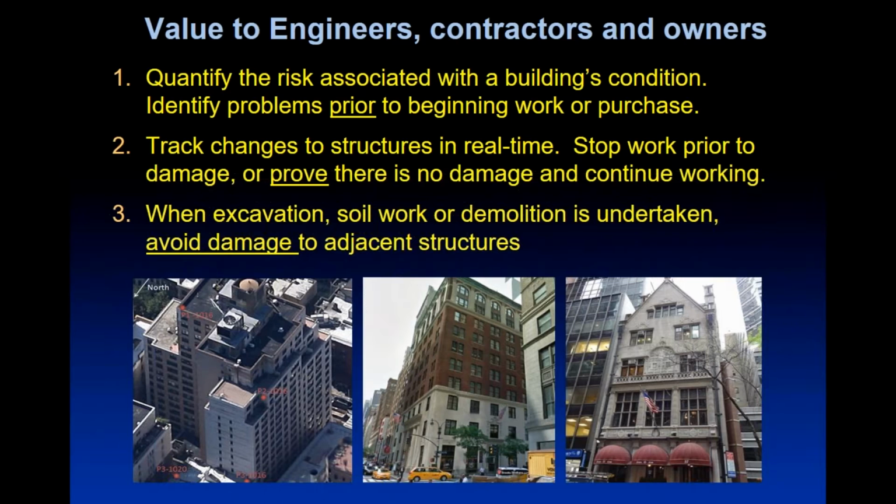Take that to the buildings department who are happy with the methodology, and you then look at where the differences from expectation are. We found some stiffness deficiencies around 3rd, 4th floor of the structure. Put that right, alter that in the finite element model, and look at the response, and then it's okay to add some extra stories on the top.